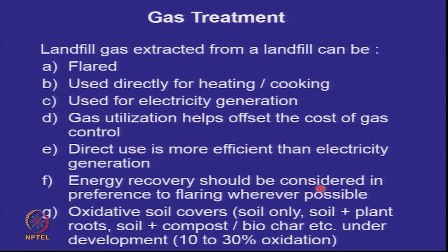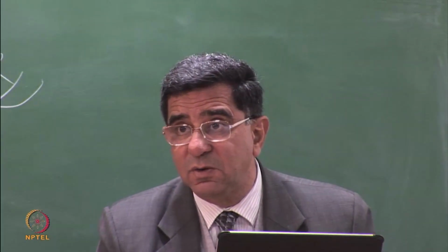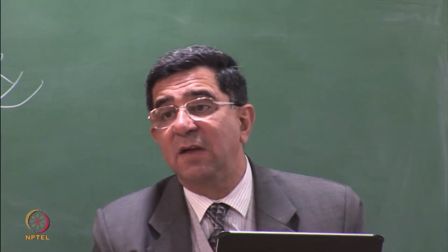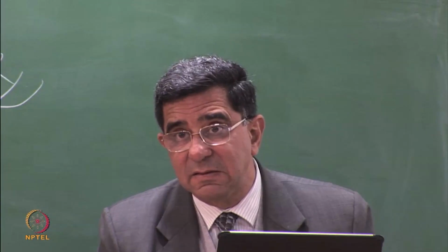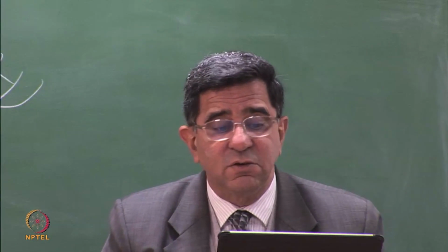So what are the ways we are using this gas? Gas can be flared. No energy recovery is done, but greenhouse gas emissions are lower. It can be used directly for heating and cooking. Heating means in cold countries, you are using hot water or you are using heating systems for heating your homes. So if you have a landfill, up to a particular distance, this gas can actually be sent as a house heating gas. Or you can send it for cooking, but deodorizing is a major issue.